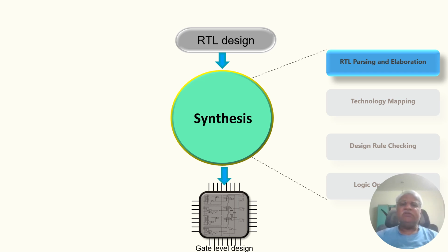So this step is further modified later as per the design rule checking and logic optimization phase. In this step, the modules are hooked and connected. Signals will be moving from one module to another as per the RTL design, and the blocks and their hierarchy, everything will be specified. Thus, this will be a ready-to-go design as far as the RTL elaboration is concerned.